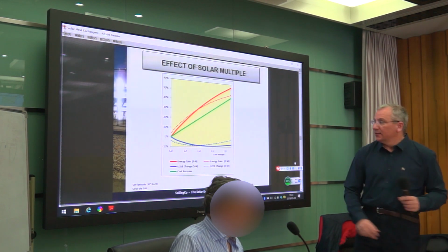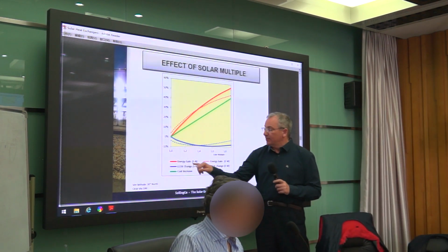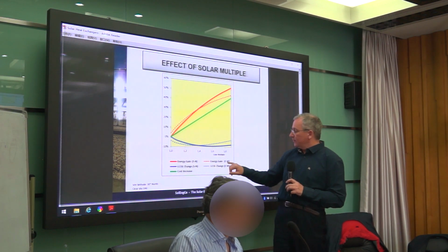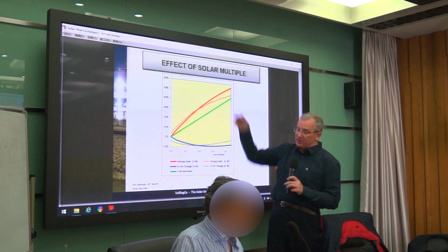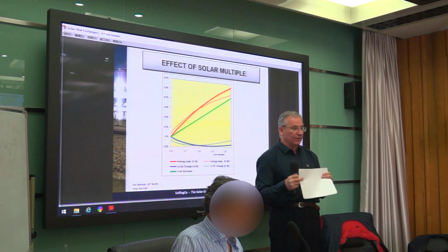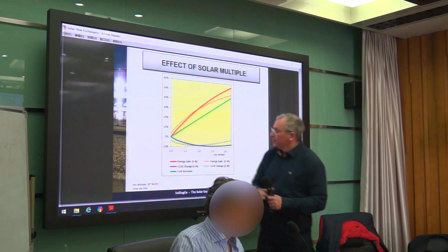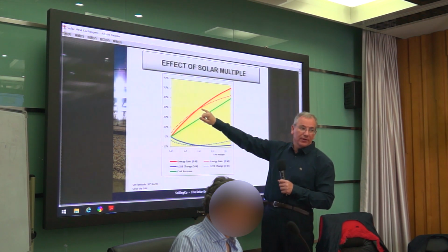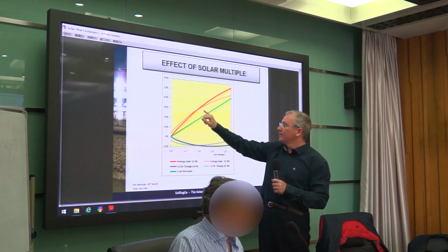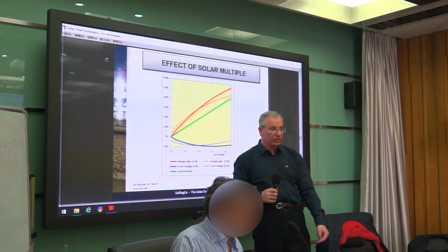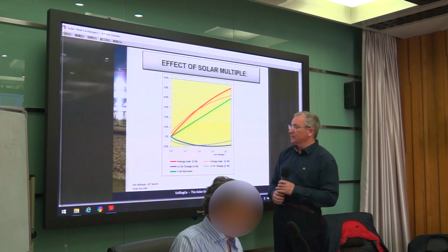So if we put it into the calculations, we talk about the gain of energy. Here we plotted it for north-south and for east-west. The red one is north-south, that's this orientation, the full line, and the dotted line is for this one. As we know, we always get more for the dotted one up to this point, and here we have the break point, which was 1.3, 1.4. And then we always get more energy from the north-south orientation than from the oblique position.